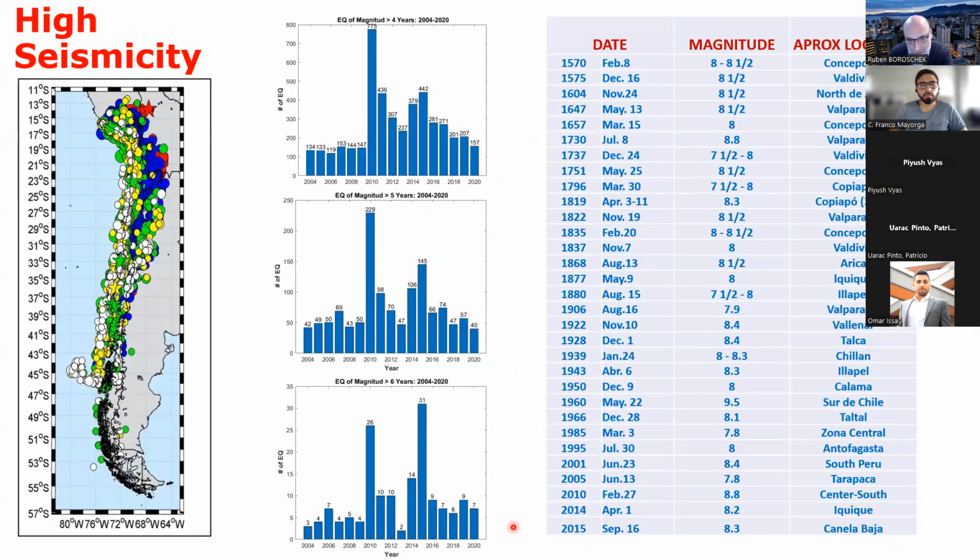Just to understand why we do this in Chile, one of the things is that Chile is a quite high seismic country. If you check, for example, magnitude 5 earthquakes that occur in a given year, these are generally produced at accelerations between 1 to 5% G or less, depending on the distance and soil conditions. But we have nearly one every week and a half or so in a year, and magnitude 6 that are sometimes closer to 5% G. Then we have one every 4 months or sometimes more than one in a month.